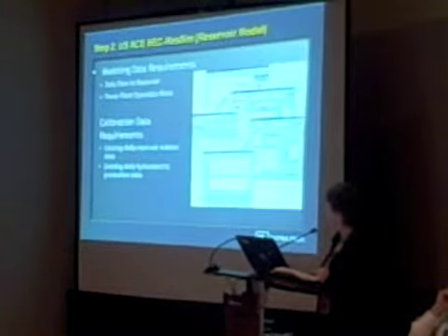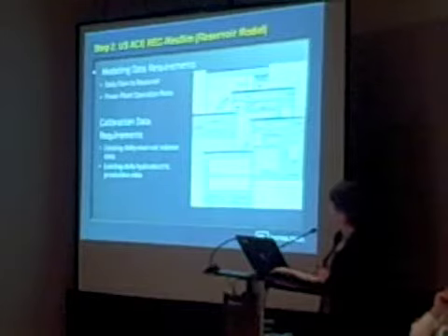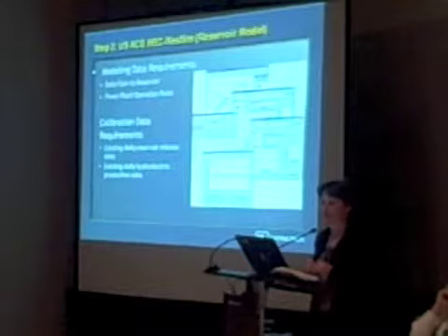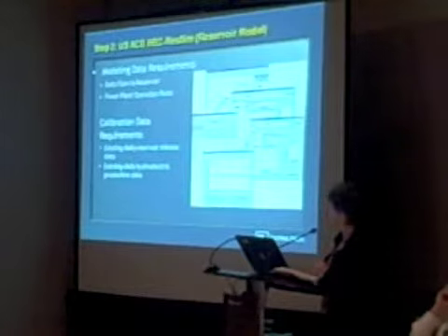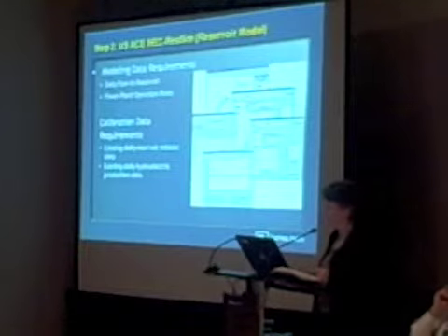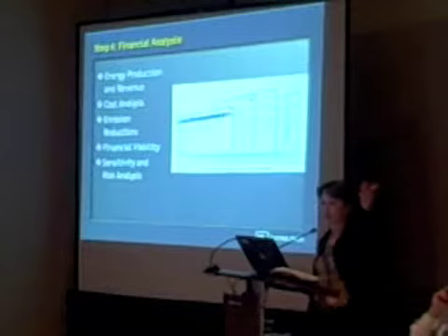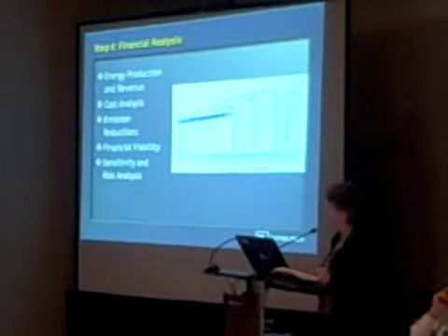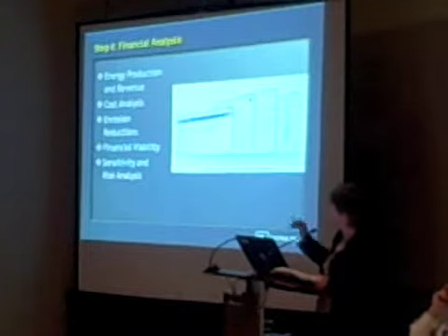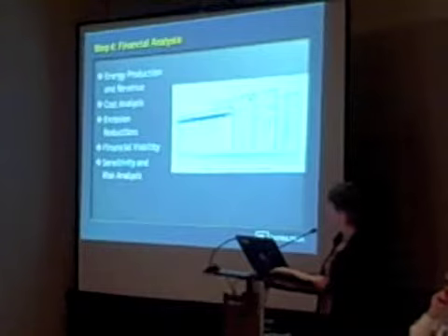They have a hydrodynamic model that you can use if you have enough inputs to model it. And then we move on and take that water into the reservoir and look at the operational rules for the hydropower plant, and we can actually come up with what the actual generation is going to look like from that plant, again in the future, in light of this changing availability of precipitation coming into the system. We can do a financial analysis to see what that means for the viability of a new project.